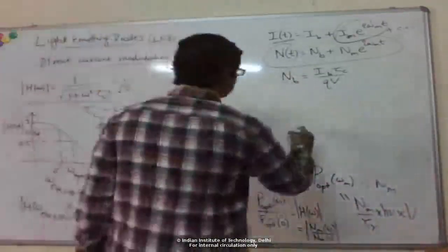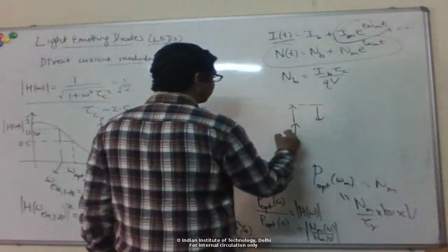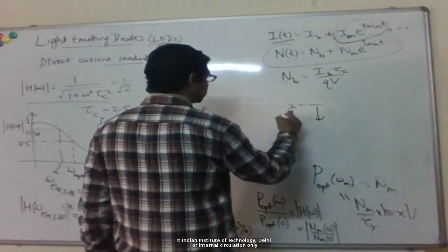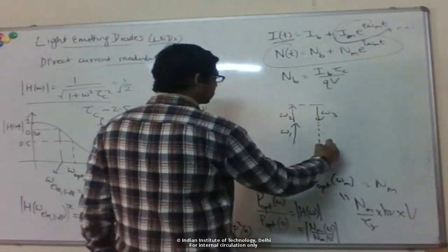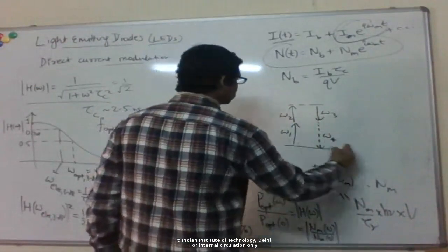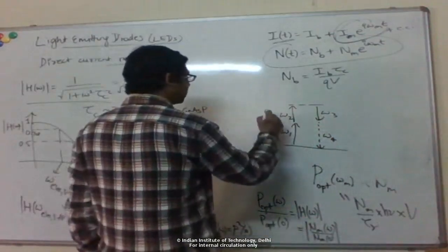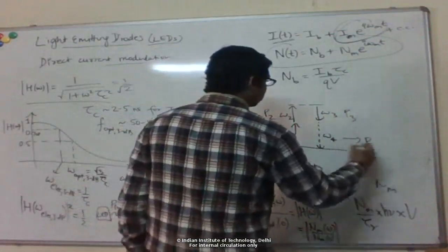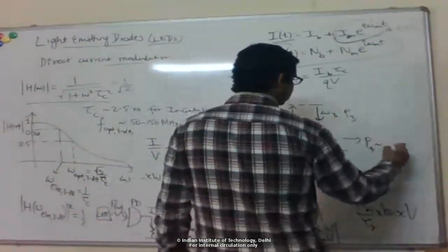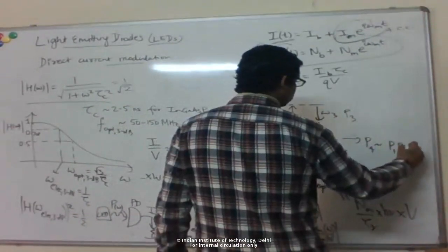So the most general case you can consider is that I have three frequencies already in the system, generating a fourth one. So I have P1 power in this, P2 power in this, and P3 power in this. The generated power at omega 4 will go as a product of P1, P2, P3.